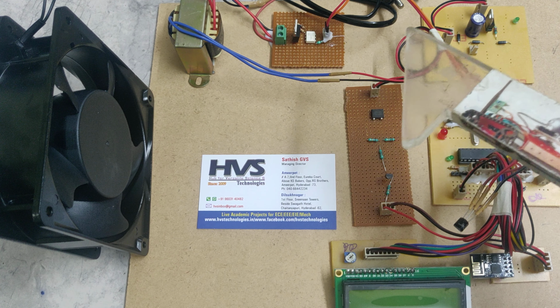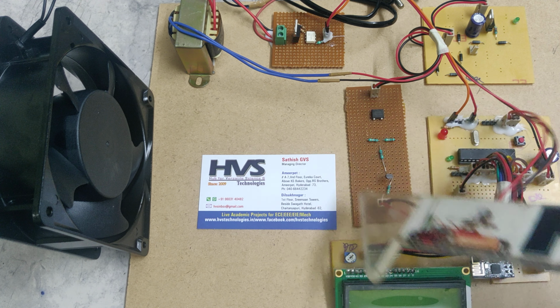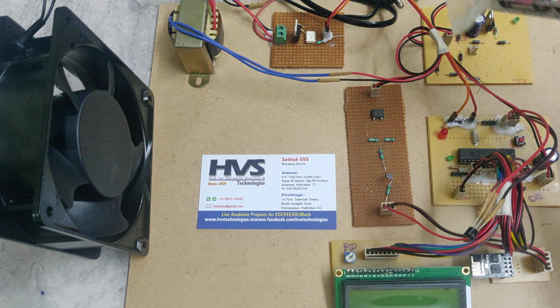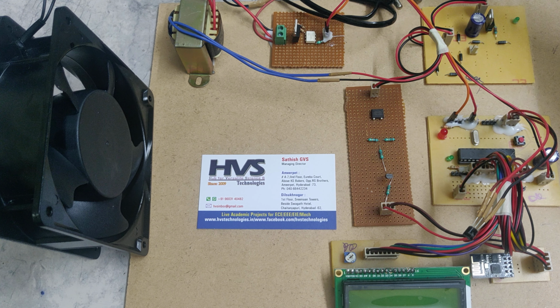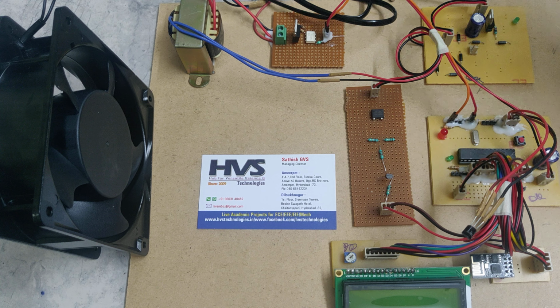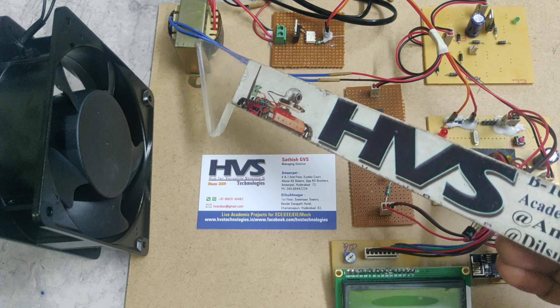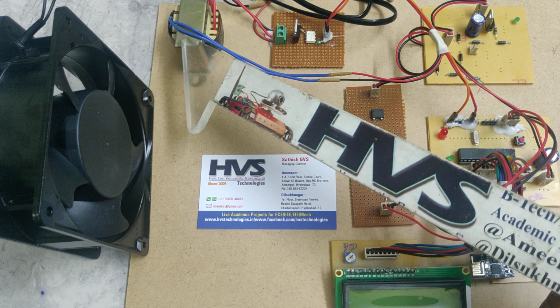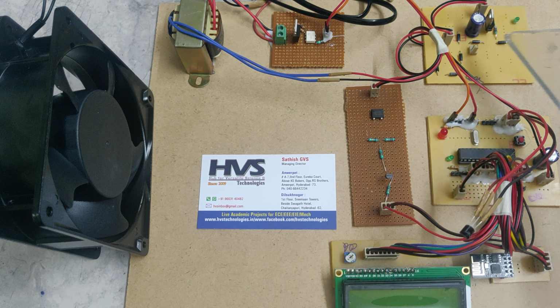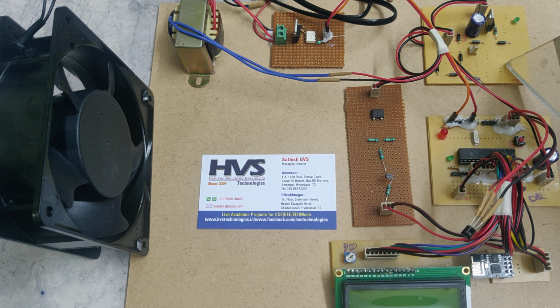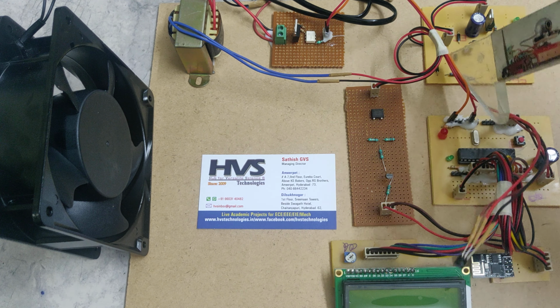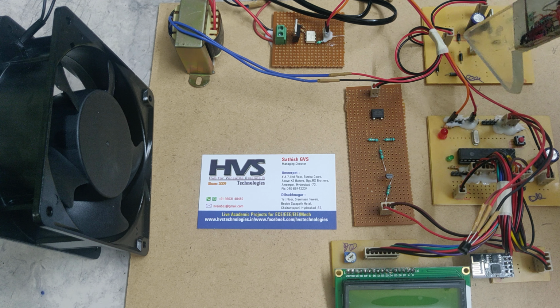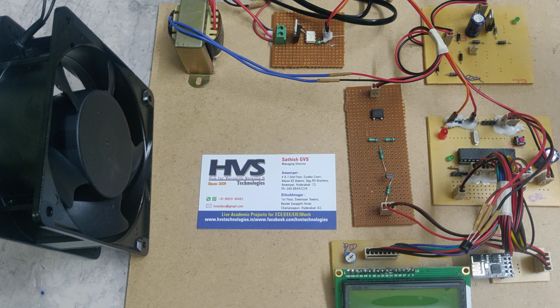we are going to detect the zero crossing using this zero crossing detector, and the whole system is powered with 230 volts. So from this cable we are going to provide the 230 volts input, and this transformer will step down the 230 volts AC to 12 volts AC, and that is input to this regulated power supply board. And on this we can see the 4 diodes are connected as a bridge rectifier, so that we will get 12 volts pulsating DC.